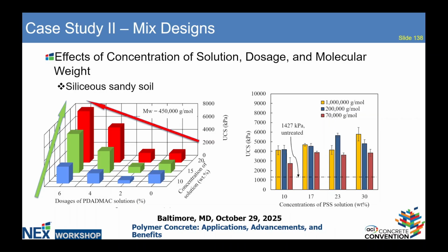They just added the polymer, treating it as cement or lime. We add 5% of material in there, doesn't matter what's in there. That caused a significant disparity in the literature. Like, why some people in the literature say, I only use 0.5% of my polymer in the soil, and it gives me a strength like 5 times higher,